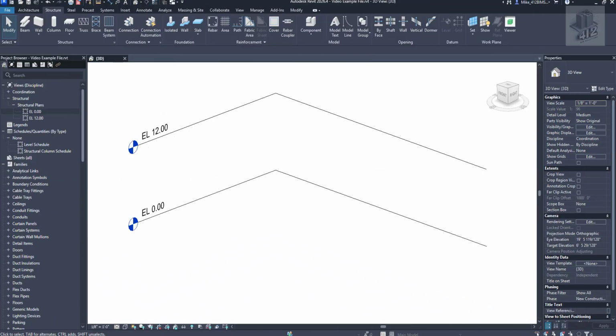In this video, we're going to take a look at steel columns and steel framing, and we'll use them to build a 12 by 20 platform. In the concrete framing video, we relied on column grids for placement, but in this scenario, we're going to place everything manually so you can clearly see the differences in workflow. Steel columns and beams use the same settings and justification options that concrete members have. The key distinction is that with concrete, you almost never deviate from top and center justifications. With steel, those justification settings matter a lot more, and you'll need to pay close attention to them as you